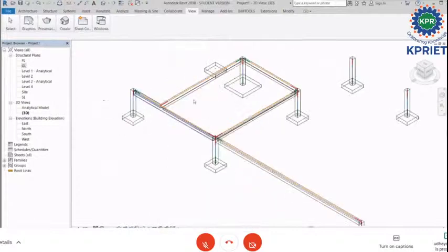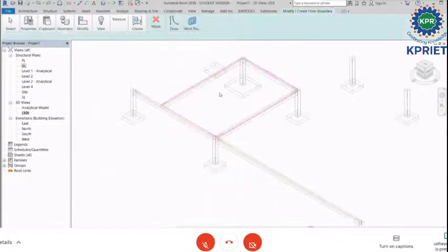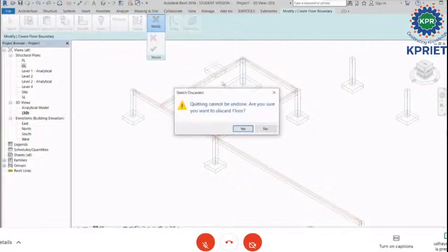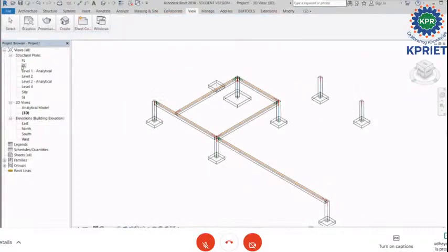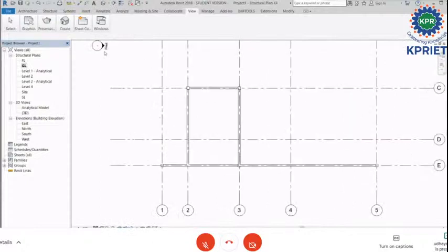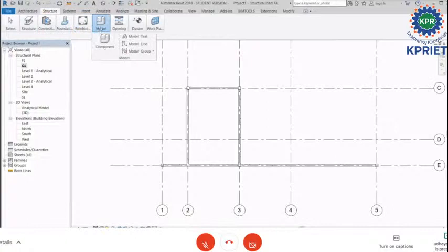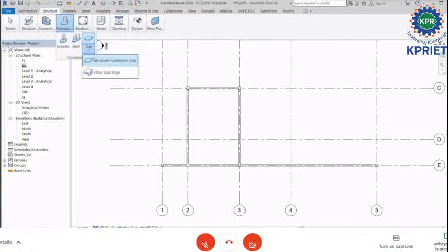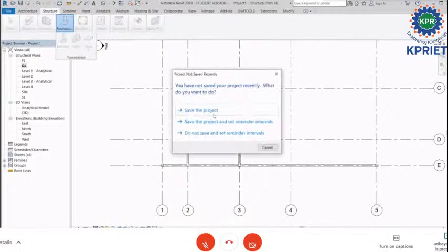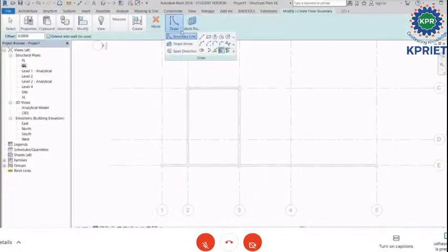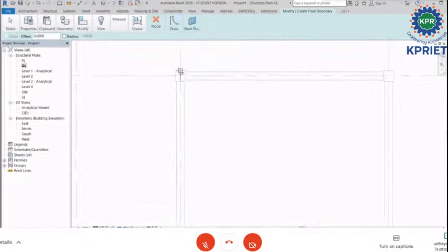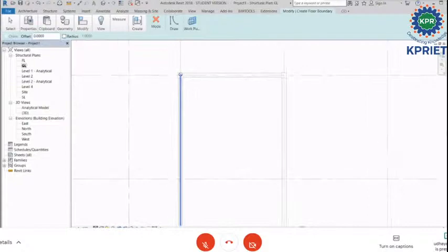Simply select this slab, automatically it will be created, right? How the slab is created: simply click the ground floor, right? Ground floor. Simply go to structural, foundation slab or structural slab, right? Same slab, any one slab, no problem. Slab. Then go to draw. You can change any slabs, any shapes, circular or any shapes, right? I simply click this rectangular. Then I draw the slabs, right? I draw the slab portions. Center to center is the right slab.